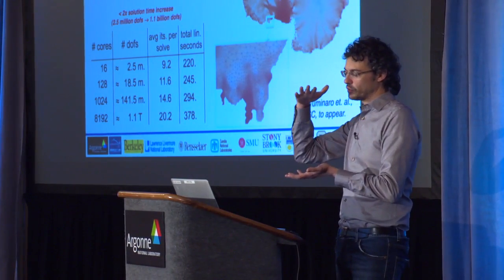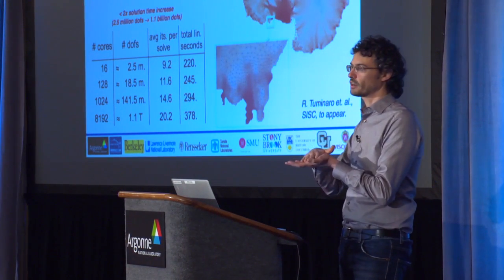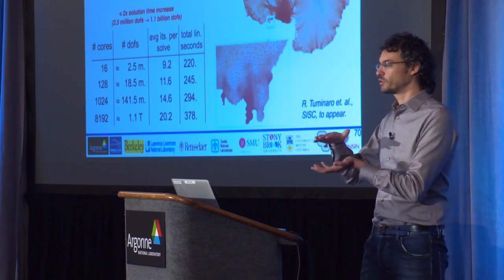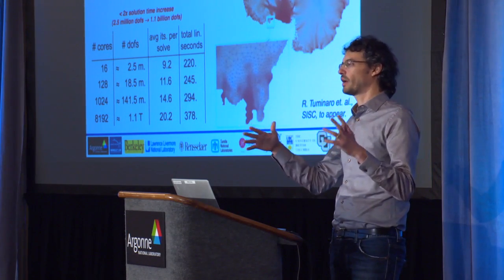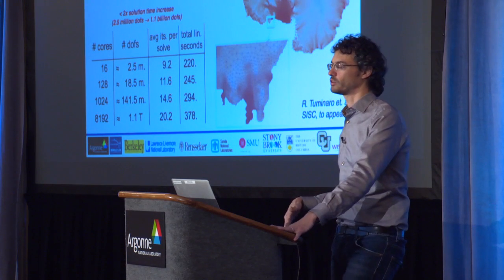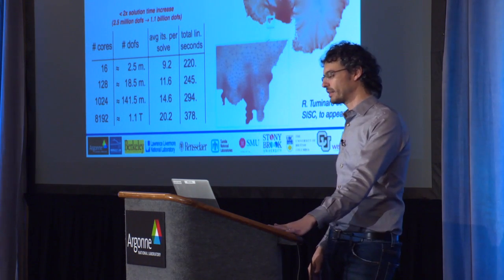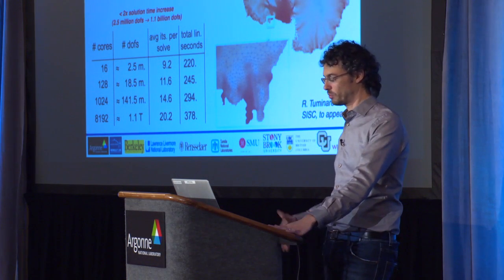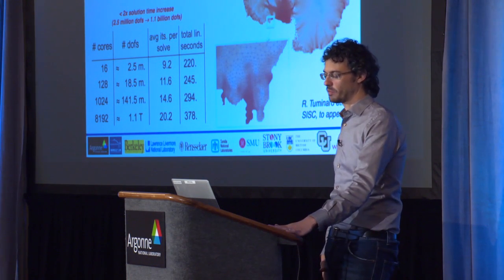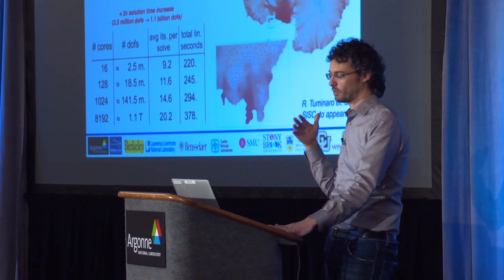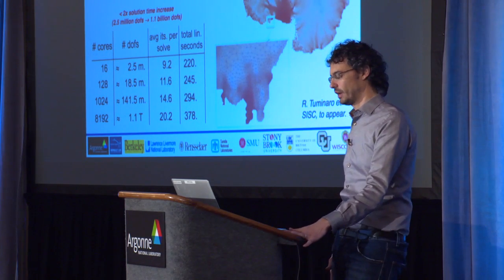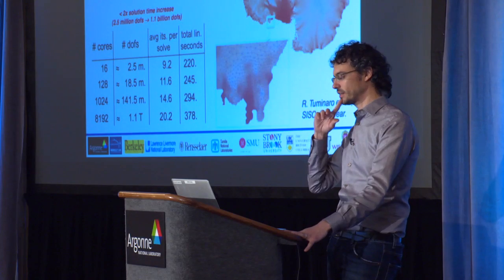You first perform a coarsening in the vertical direction, an aggressive coarsening, until you get to one layer, and then you apply a more standard multigrid preconditioner to the 2D mesh, to the 2D layer. And this proved to work pretty well. In particular, we can see in this table some weak scalability results.